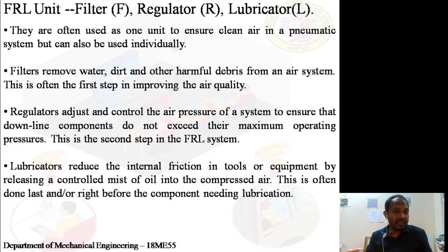These contaminants increase the friction, eventually leading to loss of functionality or complete breakage. The functionality of the compressor or any device will be greatly affected by these contaminants. So these contaminants should be removed in the filter itself. The more we can filter out such contaminants and keep them out of the track of the movement of the air, the more the equipment life keeps increasing. We will have less downtime to deal with and fewer damages.